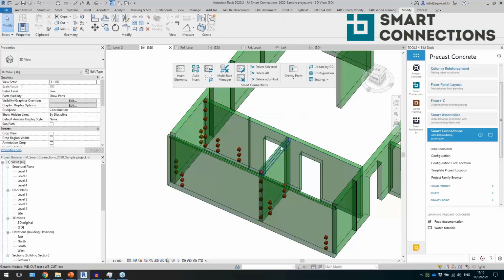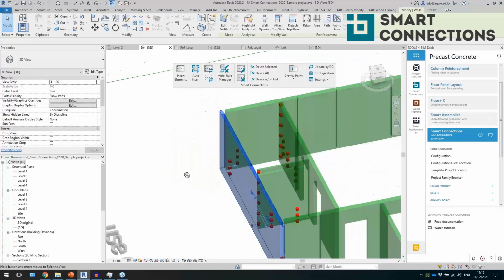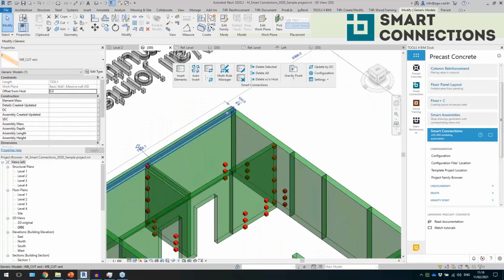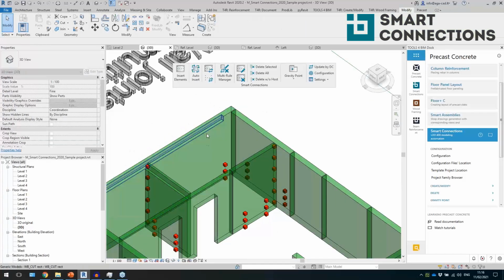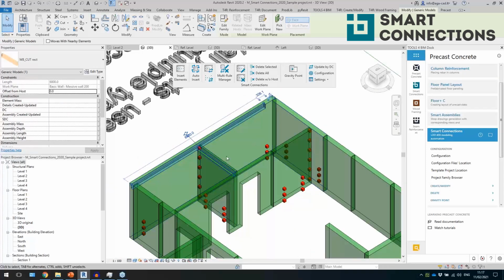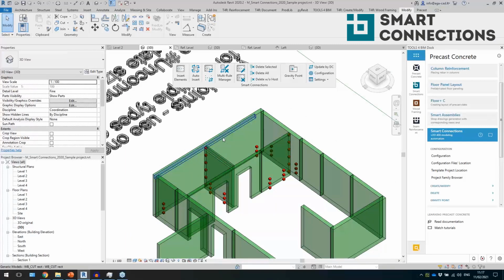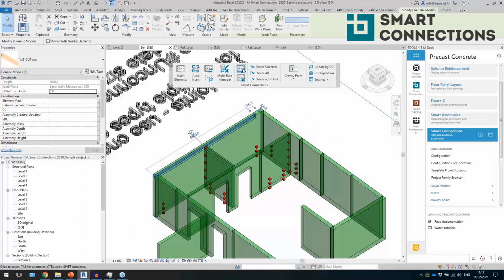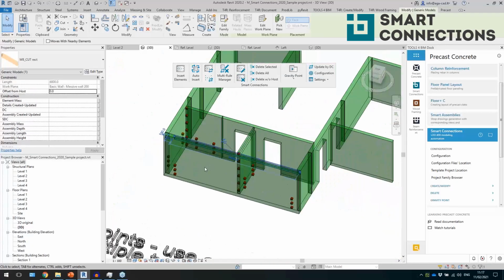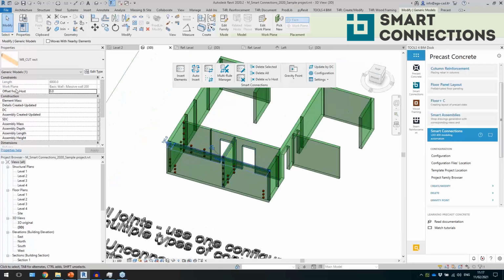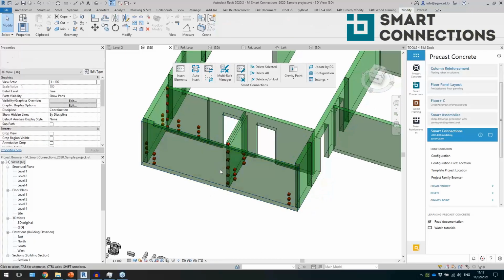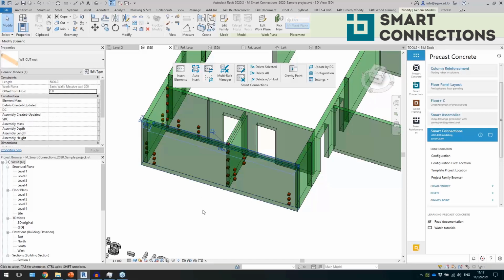I just apply this cut only for selected walls, not for all walls. So these ones don't have that cut at the top, right? So I can do that, and because these are line-based element cuts, you can easily drag them and change the position if needed, or you can modify them anytime through that configuration and make some changes. Also, the good thing about line-based elements is that you can have a count of them. You can have a length value, and you can have that in your schedules.